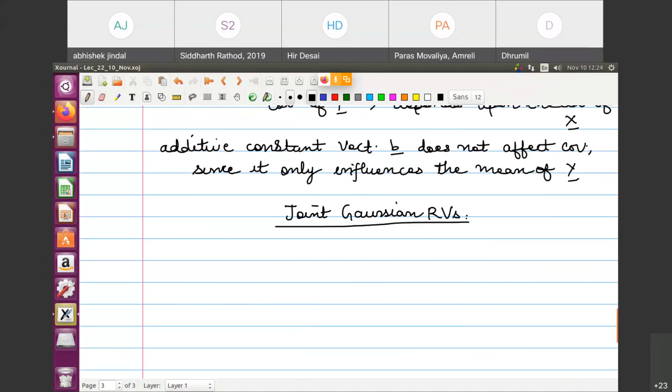So when do we call a set of variables jointly Gaussian? This is very important because this joint Gaussian word, or a Gaussian random vector or a Gaussian random process, you will encounter 99% of times in the design of communication systems. By communication systems, I would say up to 4G at least. 1G, 2G, 3G, 4G all basically struggle with Gaussian random vectors, jointly Gaussian random variables, and Gaussian random processes, because most of the thermal noise is modeled through a Gaussian white noise